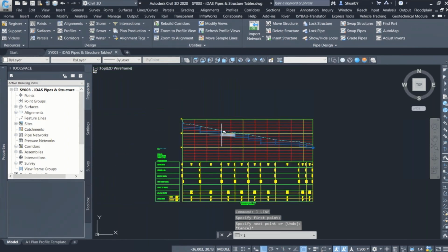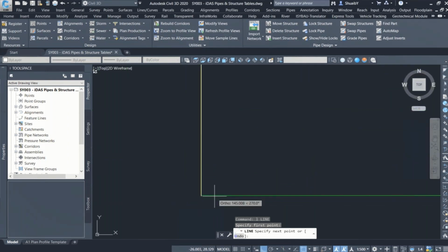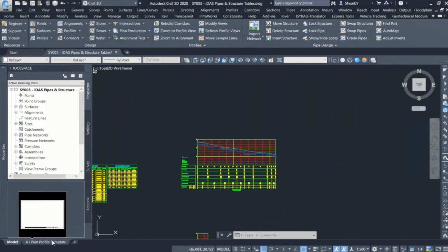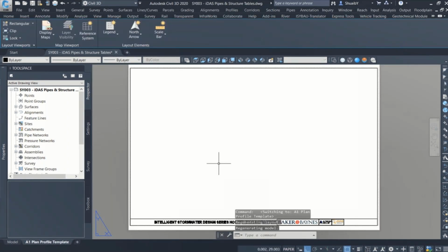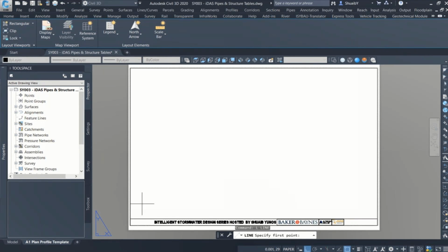And then I'm going to get the height. So I can snap to the top. This I would say is about 146 or 145. Let's say 146 just to be a bit conservative. Since we're engineers, we like to be a bit conservative, right? So I'm going to use 146 there. So I've got the length and the height. I'm going to multiply the height by 2 because that's how it currently works. And we're going to create a viewport to fit this. Again, this is just a checklist type of thing.